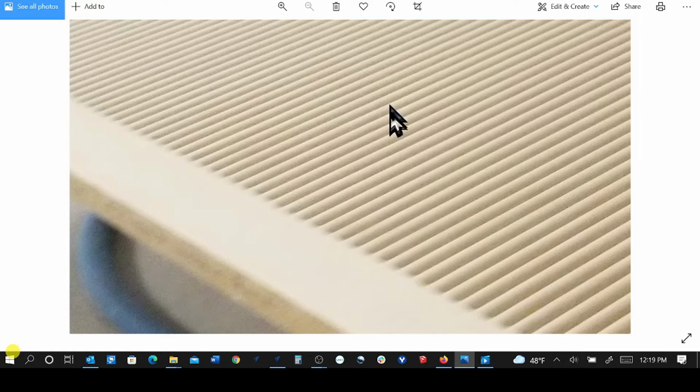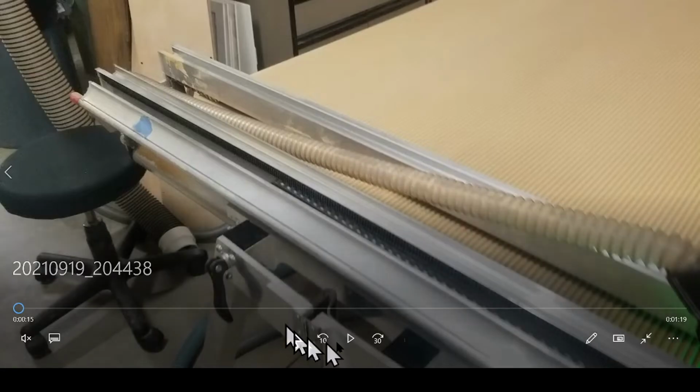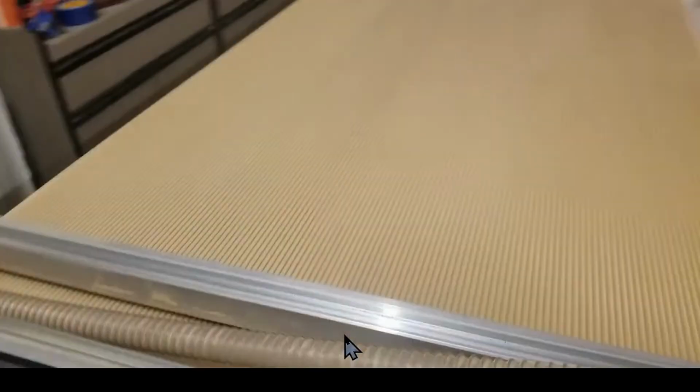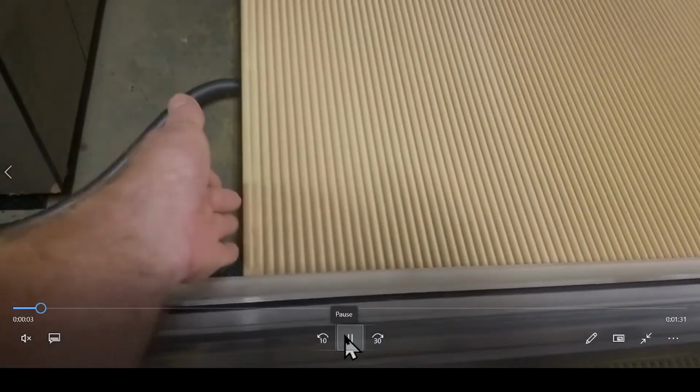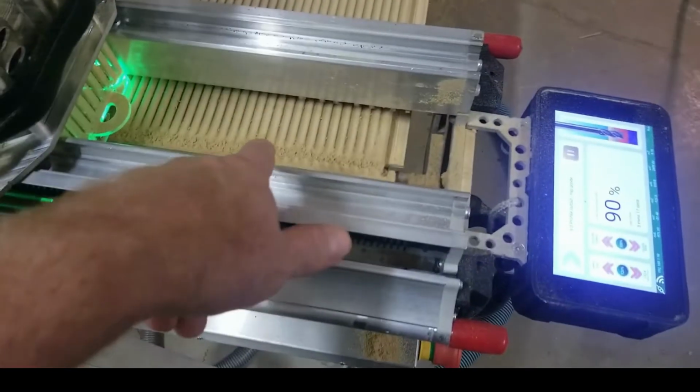This is it. This is basically a 3/8 inch rounding bit. Well, I'm sorry, 3/16 to make a 3/8 inch bead. And that's a photograph, and we'll switch over to a movie. I'll run a movie so you can see this. This is in the full 96-inch direction. I've muted the video because I haven't posted it yet. So this is me explaining the setup, going edge to edge with it, and then cutting off the edge with a 1/4 inch down spiral probably.